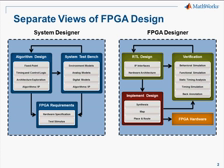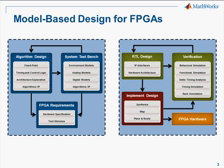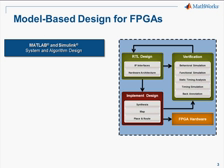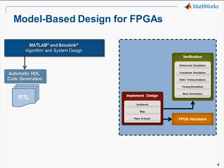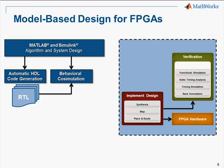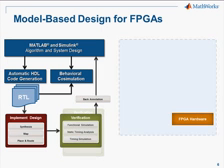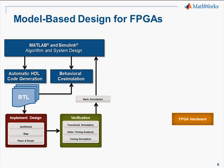So what we're talking about here today is more of a model-based design approach where instead of having different representations of the design, you're beginning with algorithms in MATLAB and Simulink. From those, you can generate your RTL directly using automatic code generation capability. And then you have the ability to verify that generated HDL using MATLAB and Simulink designs as your system test bench.